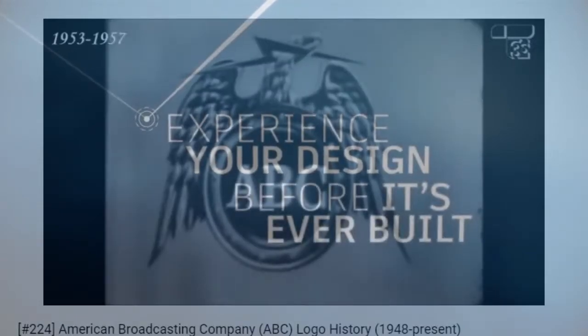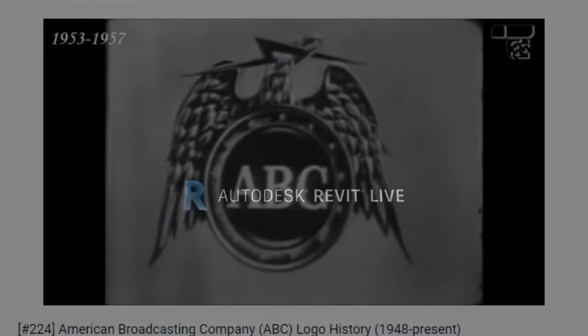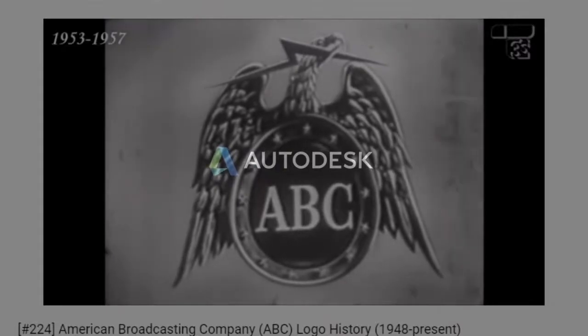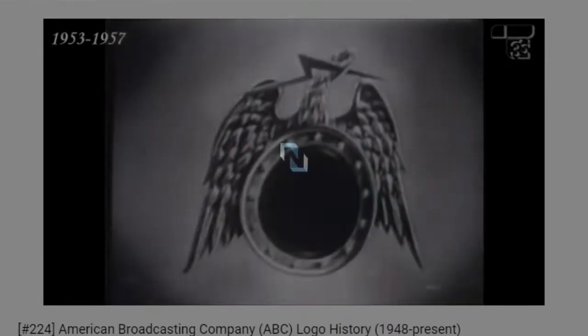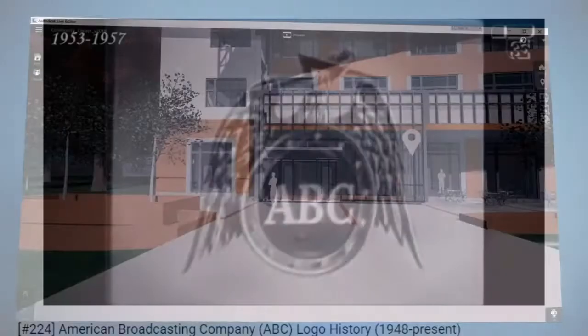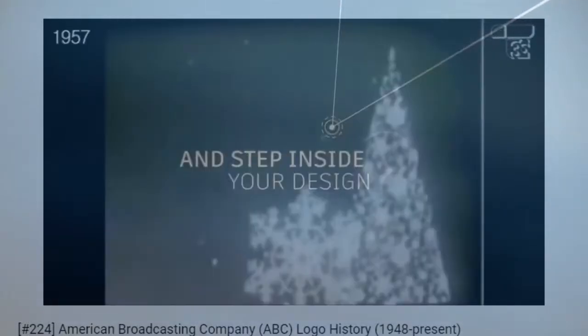Okay, so let's do that. Let's just get into our isometric view. Let's take Architecture, Component, Model in Place, Category, Floors, and we're going to call this Floor Edge hyphen level 1. Floor Edge hyphen L1.